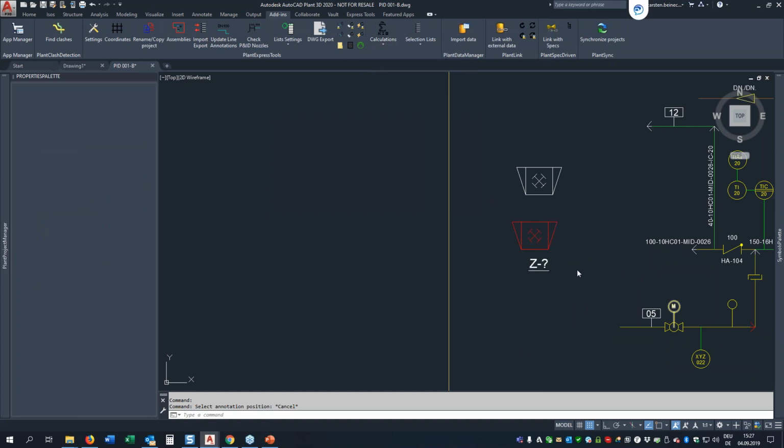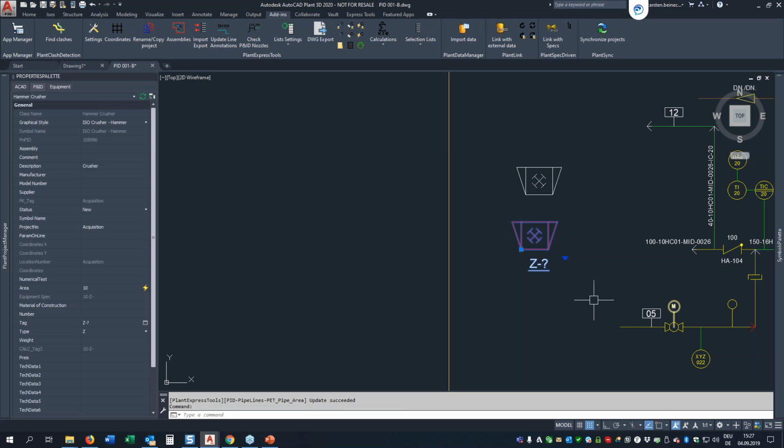Oh, no, okay. So you can use that calculation essentially for some checking. We do this for GR, where we have a property for the order status. There is also a link to an ERP system. So when you insert a symbol, the status is 0 for not ordered. Then if there is a data export from PNID to the ERP system, then the status changes to 1.